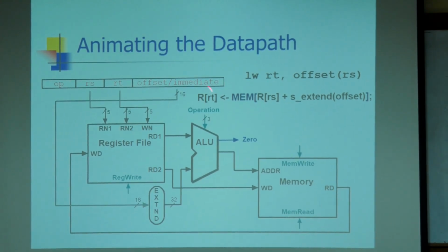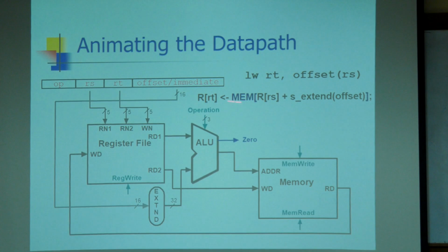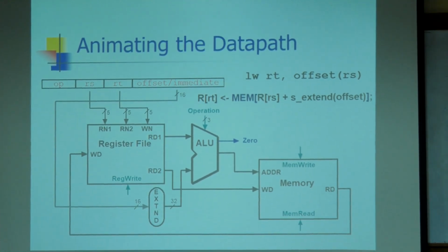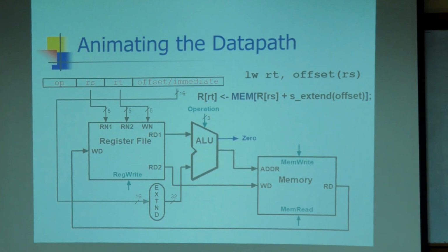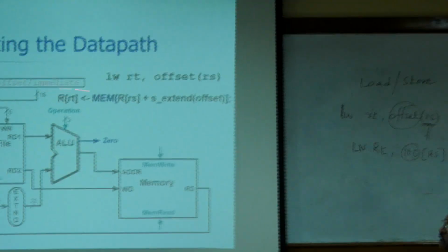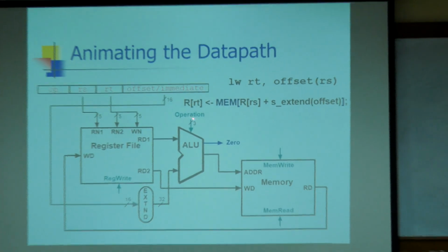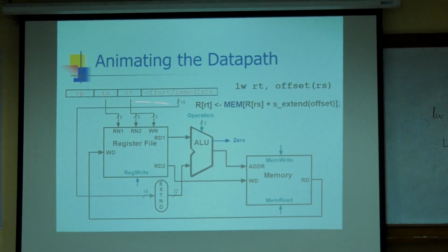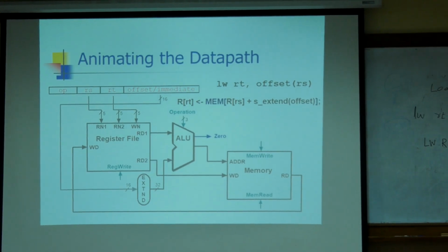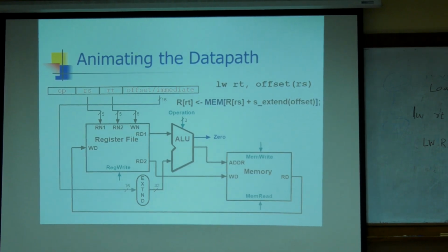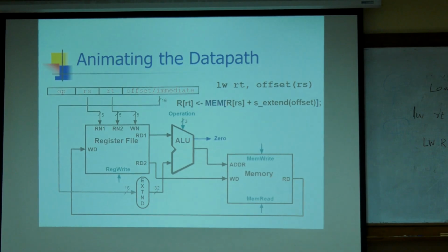So offset/immediate is there. This is in the template. Just go back again. See, this is a 16-bit offset. Offset address is 16-bit. Out of 32-bit, the total size of the instruction is 32-bit. In the 32-bit I-format instruction, the lower 16 bits will indicate the offset address.